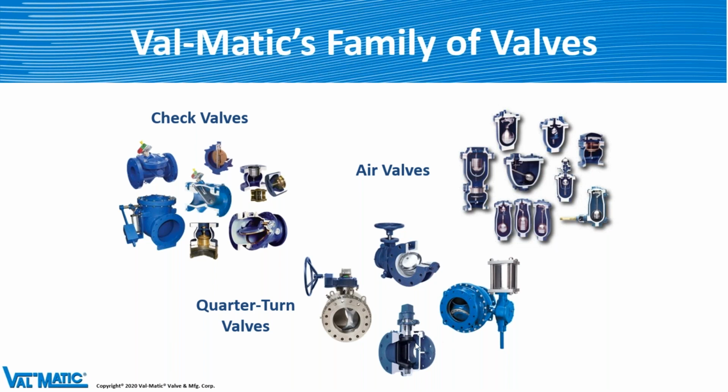Our plug valve here again is an excellent valve in wastewater and sludge applications. We can rubber line it, we can glass line it, and I forgot to say we can glass line our swing flex check valve too, in case there are chemicals or something involved. So it's great for those kinds of applications. It's very rugged. It'll last forever in sludge or wastewater.